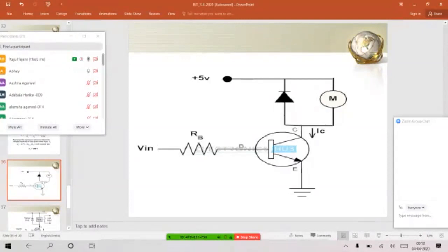It is something like running the fan motor inside the fan at different speeds depending on the weather conditions, whether you want to keep the motor running at high speed giving maximum comfort, or not; it depends on the season. Similarly, I can operate the transistor in saturation or active region and run this motor at different speeds. If you want low speed, you keep IB at the minimum required for driving the transistor into saturation, and it will run at one speed.